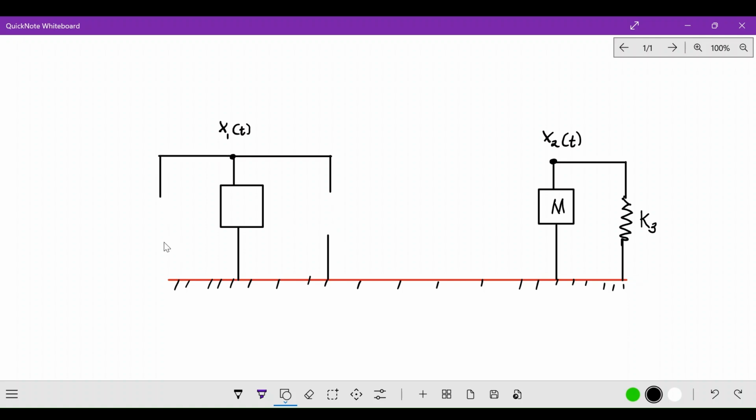Remember that all the forces transmitted through mass number 1, the spring, and the rest of the system are opposing forces. So this force here, I'm going to represent just like a voltage or current source, right? In that direction, that force is applied to this system, so it must be in this direction. So this force is F of t. And then this is m1, and there is a spring here, which is k1.